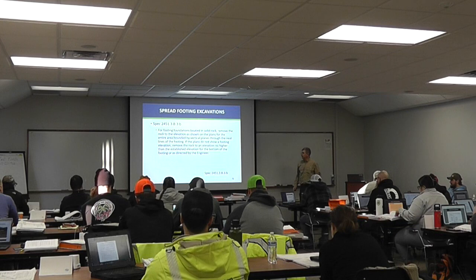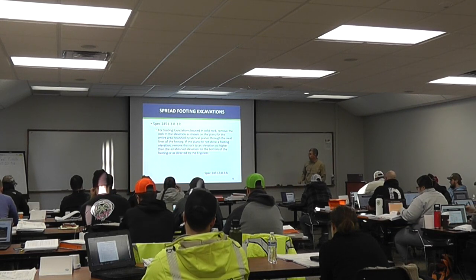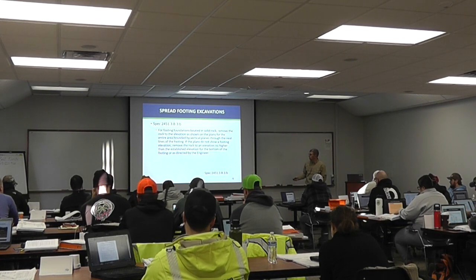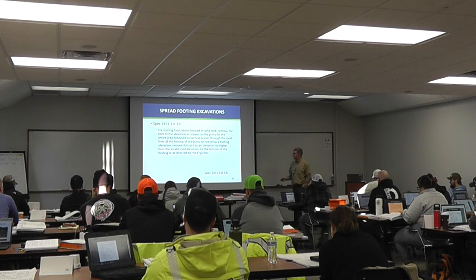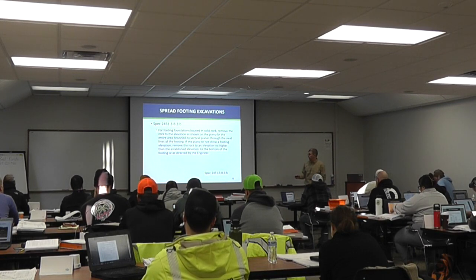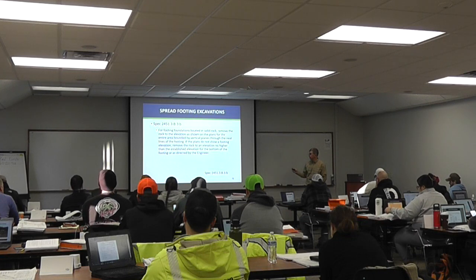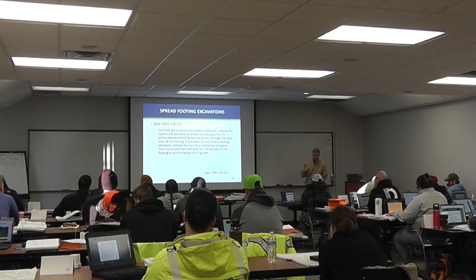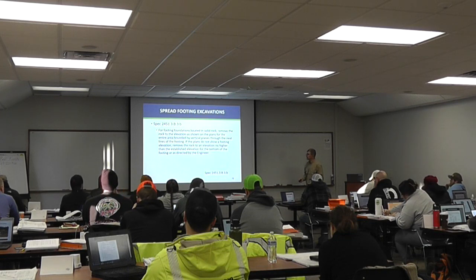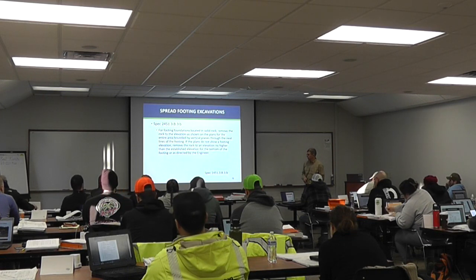Okay, for footing foundations located in solid rock, you remove the rock to the elevation shown for the entire area. If plans don't show a footing elevation, remove to an elevation no higher than the established elevation for the bottom of the footing. So this is just saying how you excavate, and particularly here in solid rock.